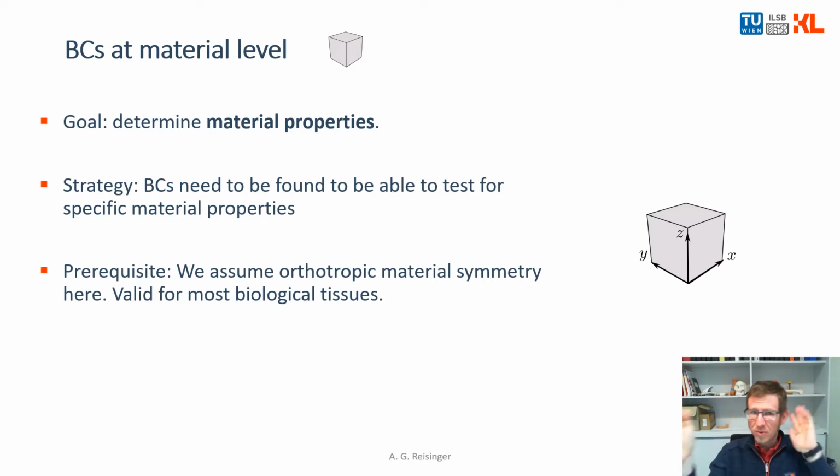the relationship between stresses and strains in your sample, and it is actually necessary to think about what your material does in terms of its symmetry. So there are different kinds of material symmetries in nature. Maybe you have heard already about isotropic material properties.